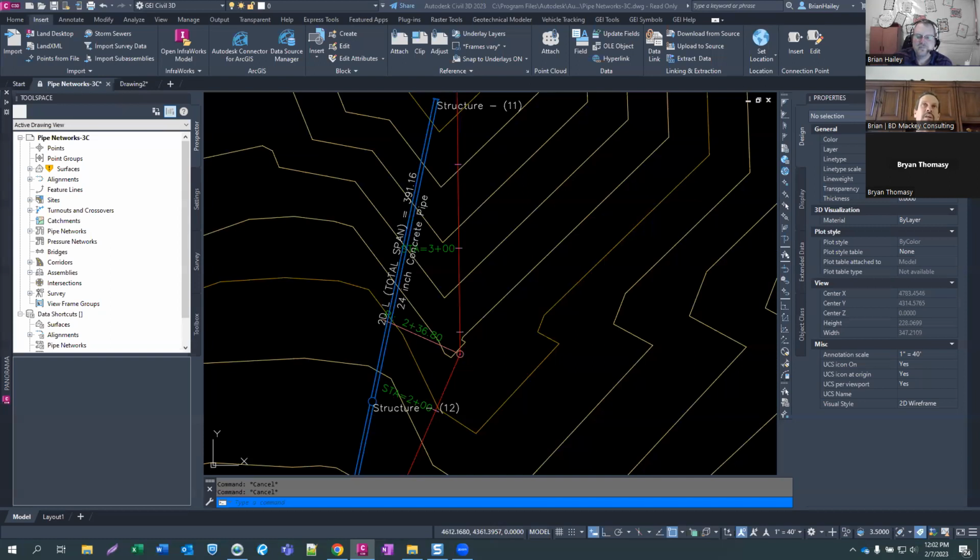When you're in Revit, it's going to export whatever you see. There's no freeze, there's no thaw. If it's on the screen, it's going to export it. So I always try to tell people you need to go in and set up a view specifically for export. In Revit, I have an entire category called my Z exports category, and I set up whatever I need for whoever needs it to be able to export it out. And like I said, a lot of times for civil guys, I turn off all the interior walls. You don't care about interior walls. You only care about maybe where there's a core and the exterior walls.